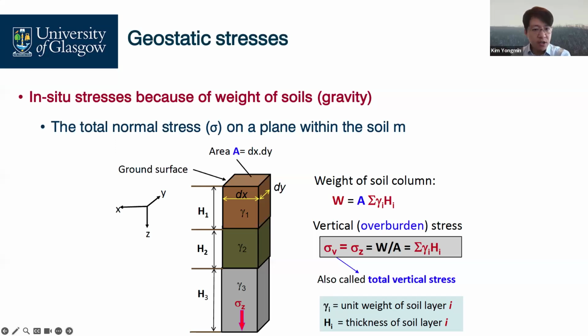So the vertical stress at this point is the unit weight of soil for each layer times the soil depth for each soil layer. That's all.